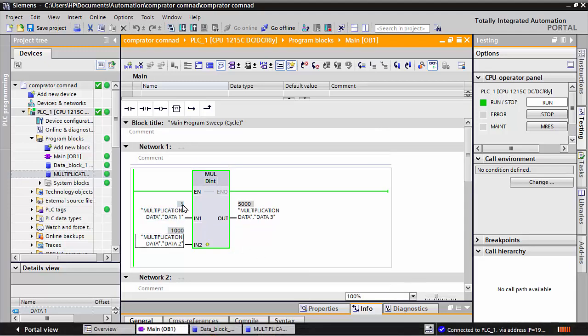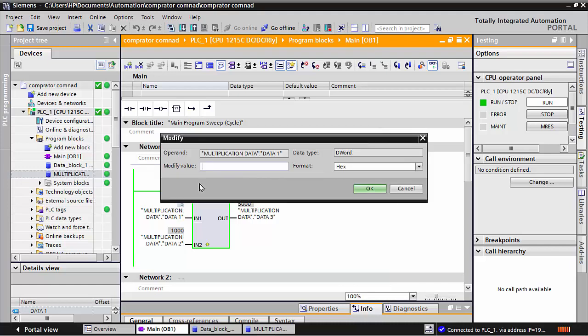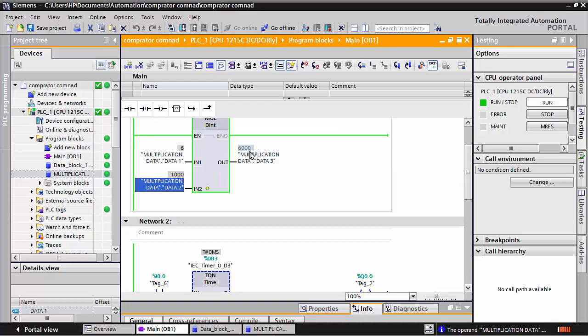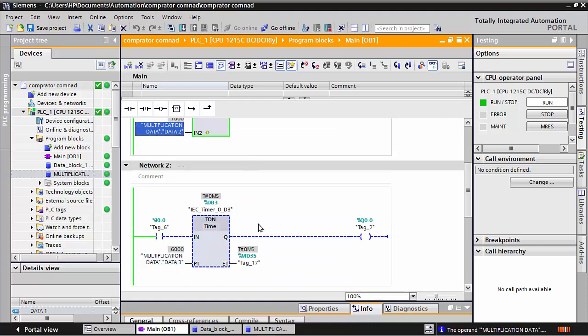And think about if I need to write 6 seconds here, I only have to put 6 here. No need to change anything, like writing 6000. I only need to write 6, and my timer will go to 6000 milliseconds, yani 6 seconds. Make it on again, and see here, it's coming 4, 5 and 6 seconds after it will change the output.